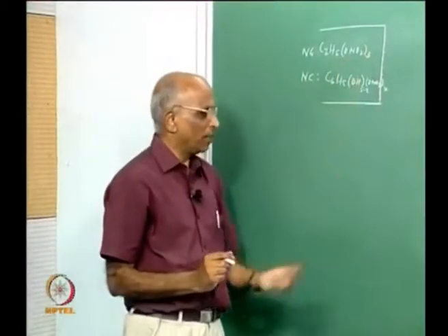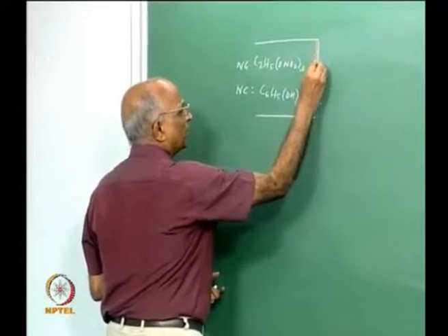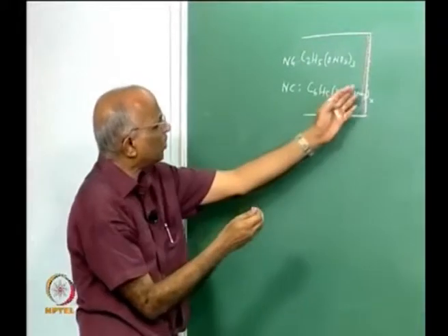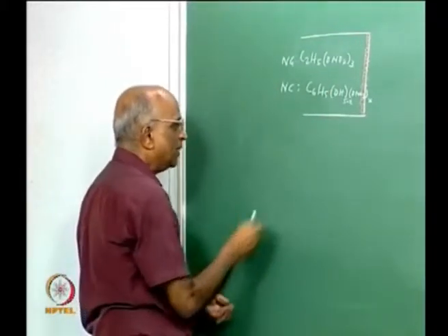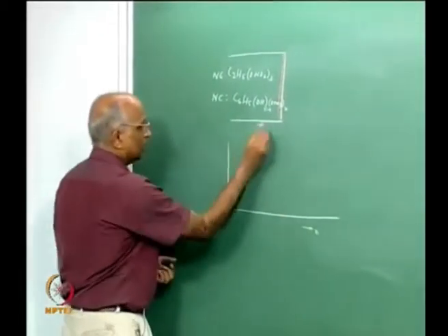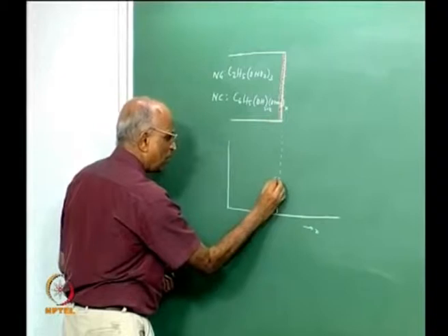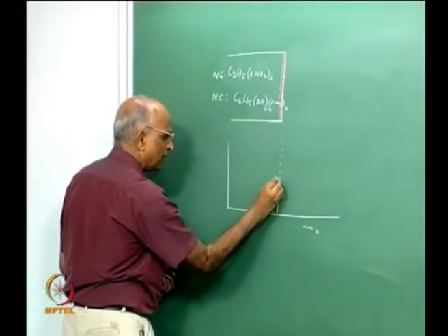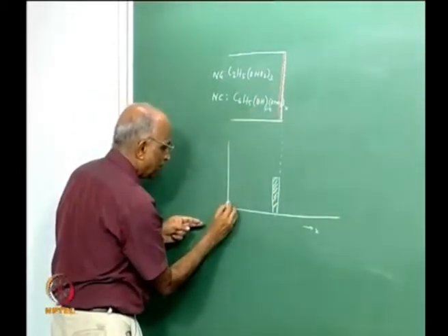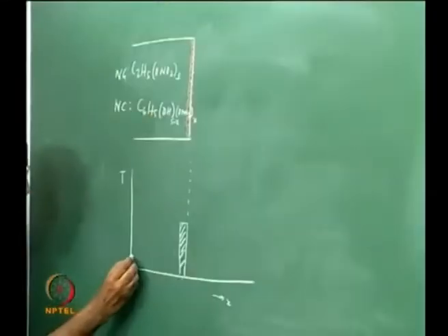Now I ignite the double base propellant, and what happens, maybe a surface very near to the surface gets overheated, because all these propellants are something like an insulator. Heat does not conduct deeply into it, and therefore if I were to consider this as the scale X along the distance, and this is my surface over here, a small thickness of the propellant surface gets heated when I heat the surface, and therefore my curve, if this is my temperature axis on the y axis and this is my distance along, will be something like this.